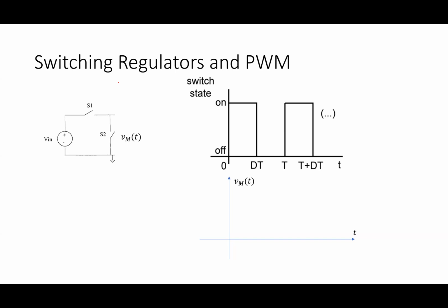Basically, if I put a voltage VGS onto that thing that's big enough, it's a short circuit. And if I take a VGS off of that thing, it's an open circuit. So it's basically a caveman sort of thing where it's on, off, on, off, on, off. Very simple. That guy right there is a single bit memory, right? If you go into a RAM in a computer, it's basically just a bunch of switches like that. And it's a very simple sort of device. This is a very simple digital system in a way.